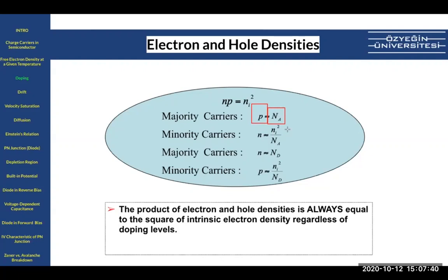If we have majority carriers as phosphorus, then we have that many electrons available in the structure because we're doping with them. Each added atom creates one electron, right? If we add another structure with 2 electrons available in its outer shell, then this would be 2n, because it is 2 electrons times each atom. And when we dope it with phosphorus, we look at the minority carriers using this formula.